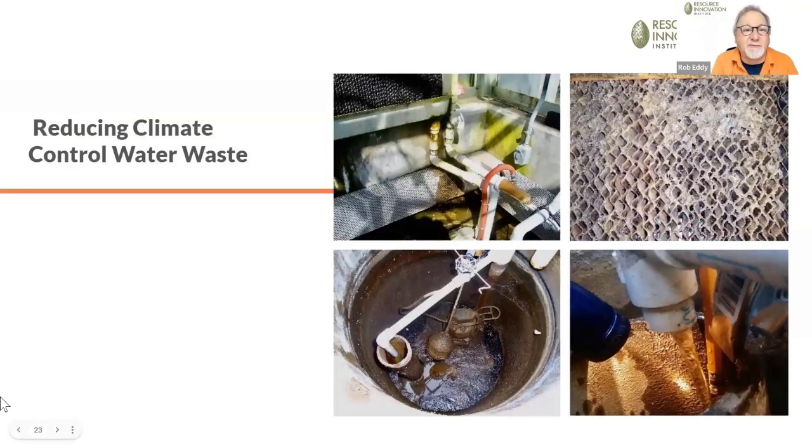Apparently, I'm the only one who takes pictures of what evaporative pads look like 2 years later. Of course, it depends on the quality of the pad and the quality of your culture of your employees. But this is what they often look like. They're leaking like heck. Some of those leaks cause algae slicks on the floor, which are dangerous. The evaporative pads can actually get biofilm, scale, algae growing on them.